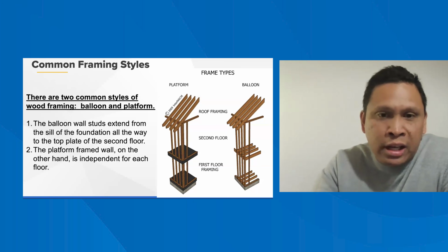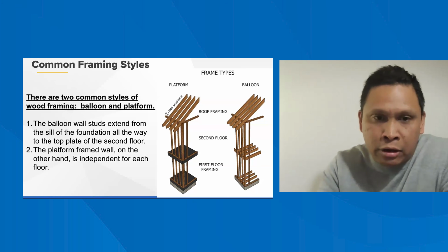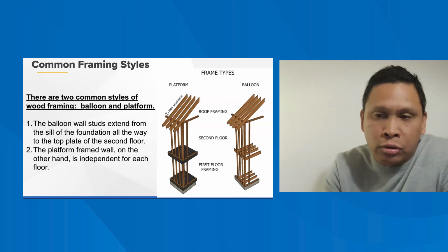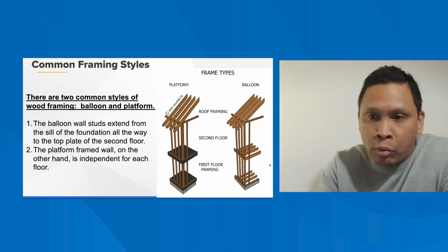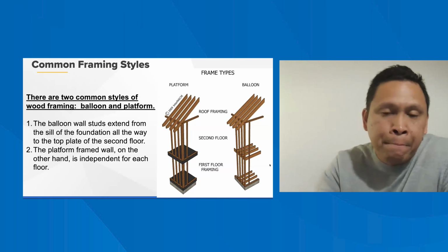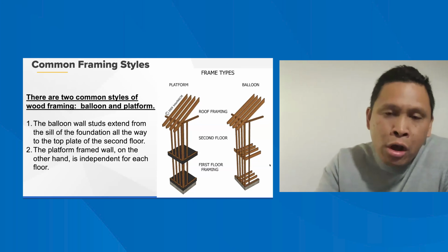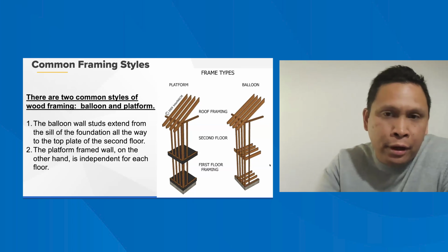Let's see here. So floor joists, again, as mentioned, come in different types that a particular builder can use, or that you would just encounter when you are out and about: solid dimensional lumber, I-joists, or open web floor trusses. Just take note of the different types of joists that I just mentioned.